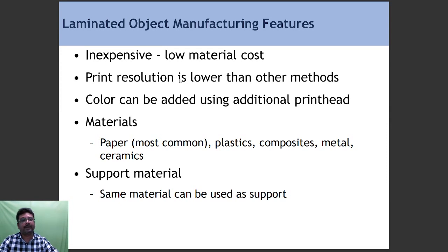The drawback is that this is highly expensive. The initial setup cost is very high, but the material cost is very low. Print resolution is very low compared to other processes. Color can be added, but additional printers are required, and those printers are also costly. Paper is most commonly used here.